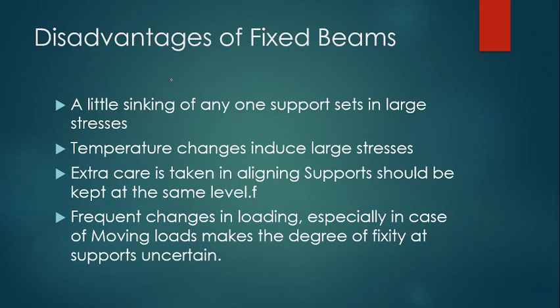But it has some disadvantages also. A little sinking of one support sets in large stresses. Let us say this is a fixed beam, and if one of the supports sinks, let us say the right side support sinks by some small amount delta, let us say delta deflection, then automatically with the effect of this sinking, additional moments are generated within the beam.